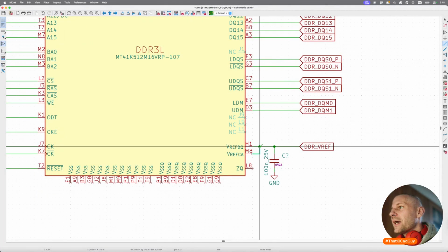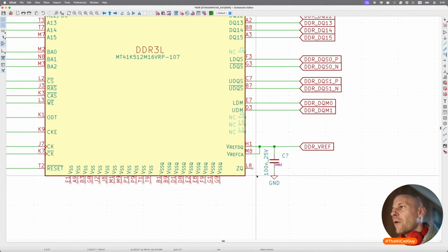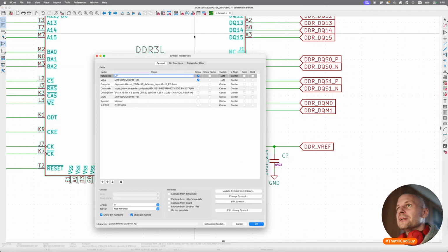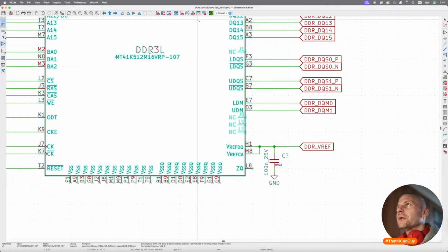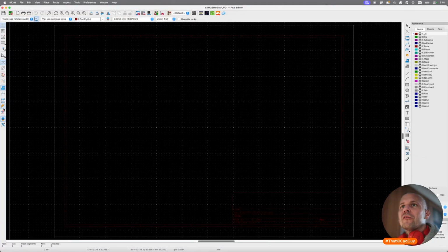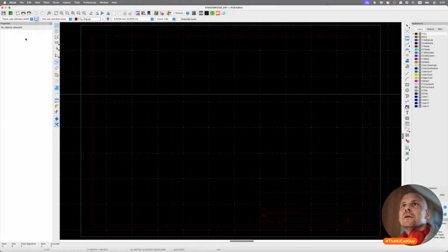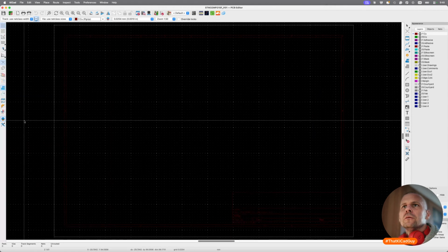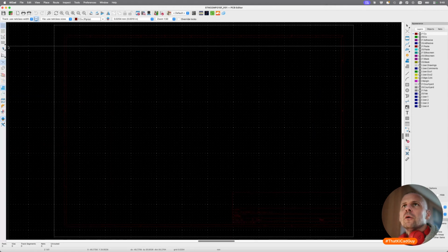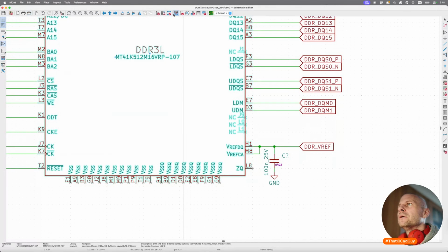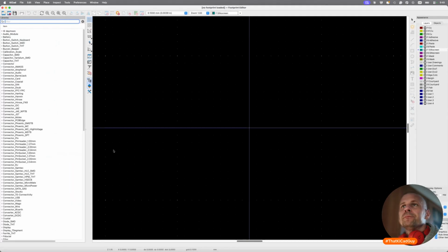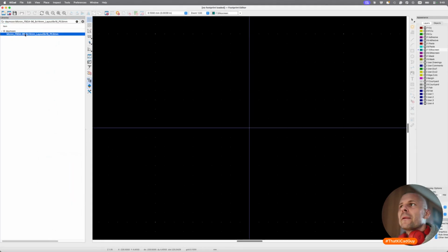That's finally starting to make sense. Do we need 2 caps or 1 only? H1 and M8. Let's check the datasheet, the footprint. Where are H1 and M8? If they are too far from each other, what did I do? No, PCB editor. Footprint editor. Here.